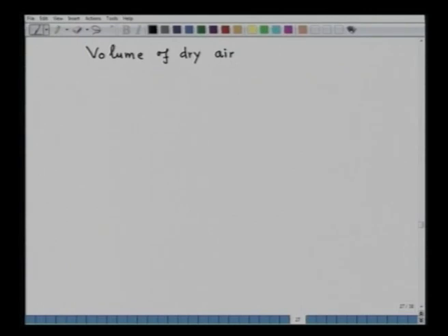Do you recall from the earlier lectures on gasification or carbonization, where I said that to determine the volume of dry air, you have to do a nitrogen balance? You can argue, sir, oxygen balance can also be done, but remember oxygen is reactive. Where it has reacted you do not know, and it is liable to lead to mistakes.